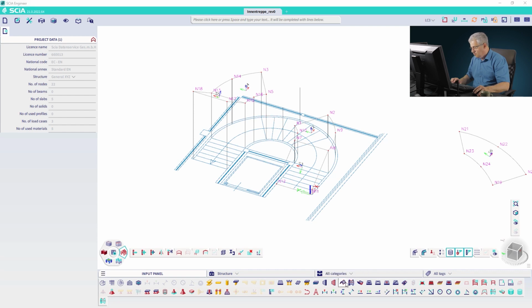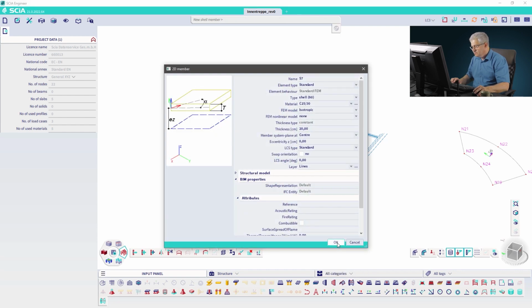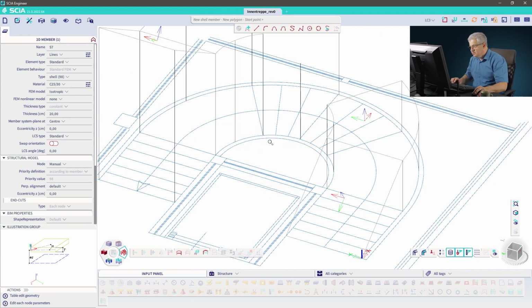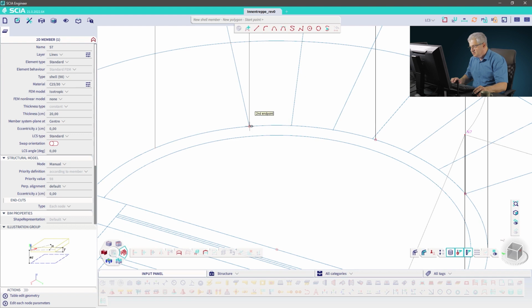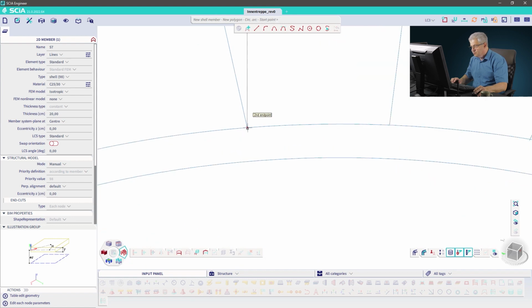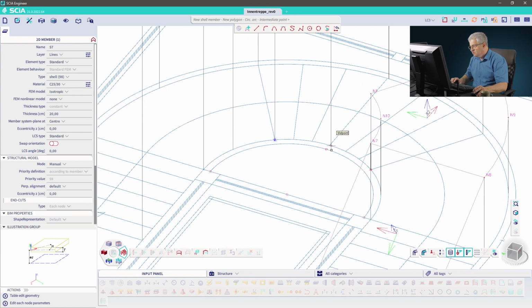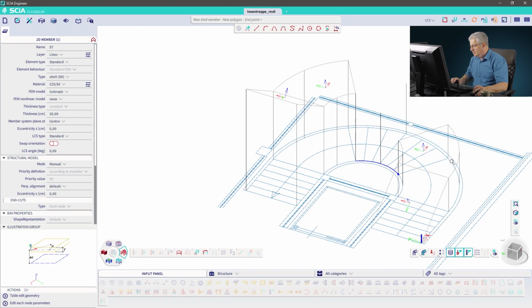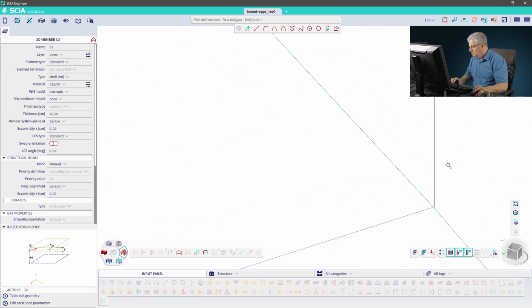So you can draw a shell as before, but I don't have these vertical lines, so I draw it only in this XY plane. I start with an arc from, I have to zoom, from this point over the midpoint to this one. Then I am again in a straight line.